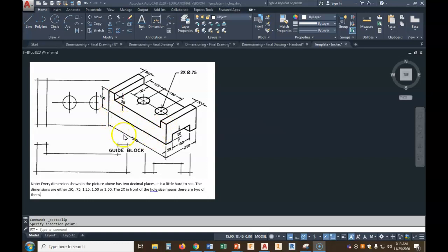It's a U shape. And a lot of times, actually about 99% of the time, our biggest dimension will be the width, okay? So that's going to be our front view, which is good. Well, look, we've got another slot cut here. This is the right side. If this is the front, this will be the right side. So we've got to draw it because that's where it's visible.